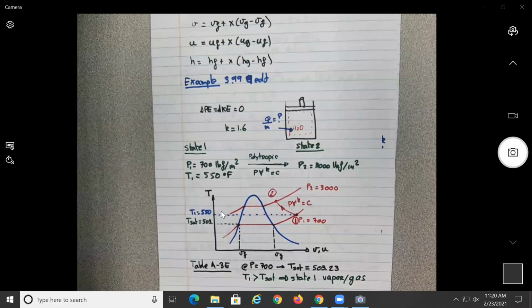So the ideal gas substance means that if a substance is within one state, the property should not change much, if it doesn't change state. The farther away you are from this line here, probably the better the assumption is for the ideal substance, and you can be farther away in any direction. But the closer you get, the ideal substance assumption is probably not good, and it can definitely not be applied when you are in the mixture area, no? Because the substance is at two different states at the same time.